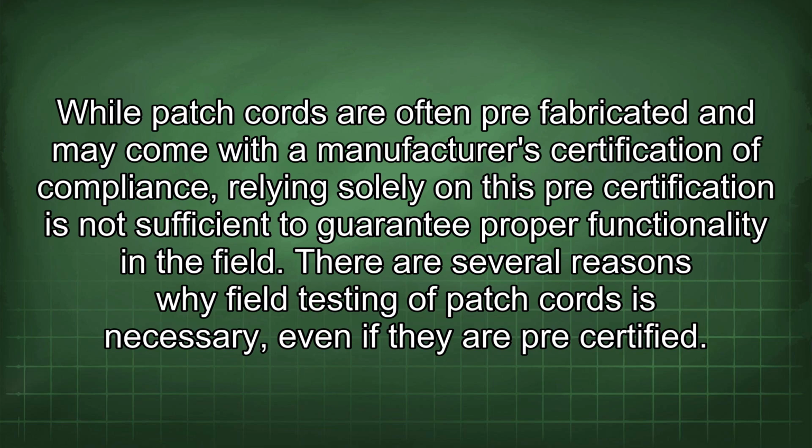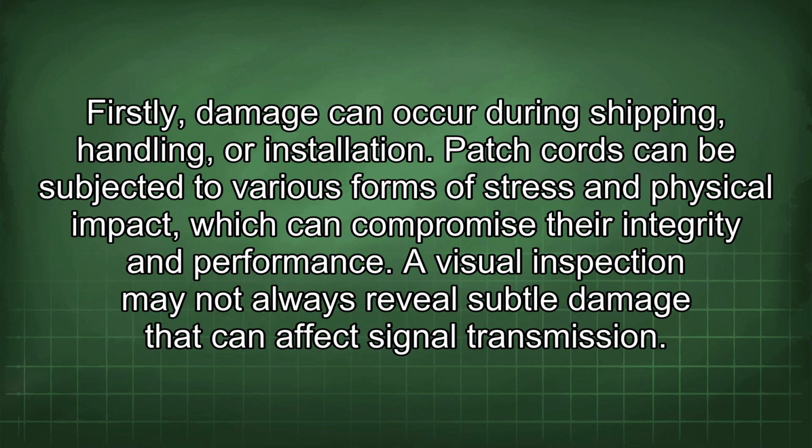There are several reasons why field testing of patch cords is necessary, even if they are pre-certified. Firstly, damage can occur during shipping, handling, or installation. Patch cords can be subjected to various forms of stress and physical impact, which can compromise their integrity and performance. A visual inspection may not always reveal subtle damage that can affect signal transmission.